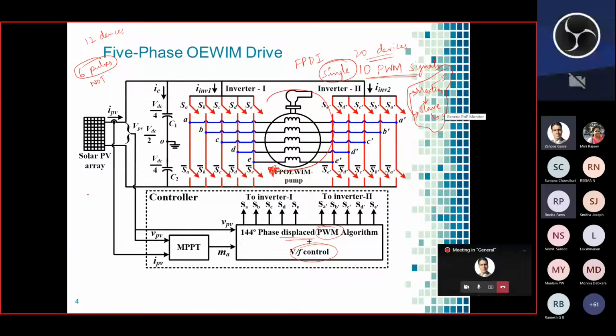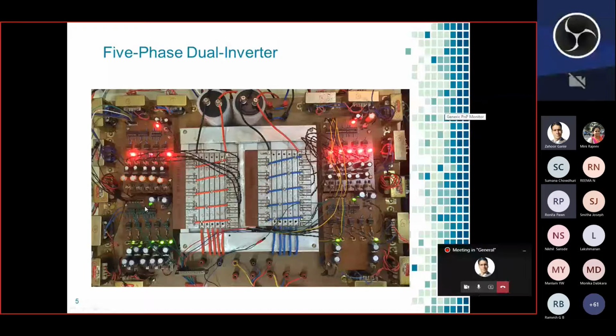So we thought, why rely on a company that charges more for us? We just wanted to make our own inverter. This is the inverter which we made in our lab. It is an indigenous inverter, completely made by us in the laboratory. It has these gate drive circuits. These are the gate driver circuits; you can see 4 gate driver circuits for top switches and bottom switches separately for 2 inverters. These are the 2 inverters in between. With the red and blue wires you can see 5 phases there, and DC link capacitors and the logic power supply also.